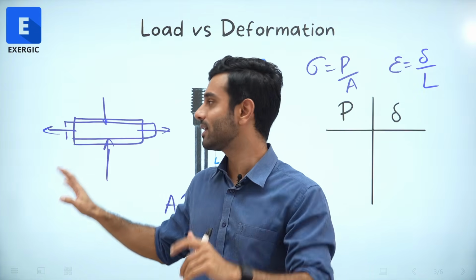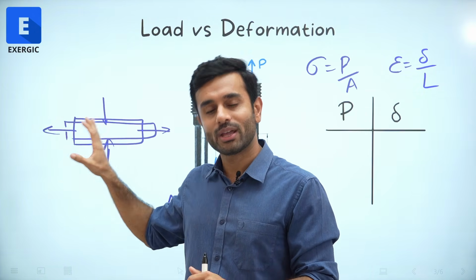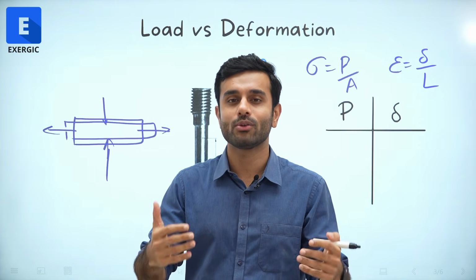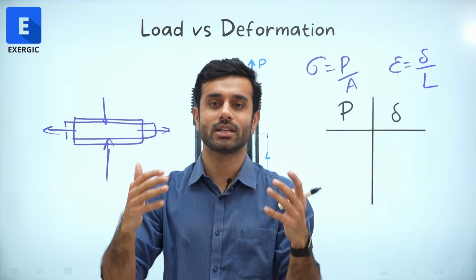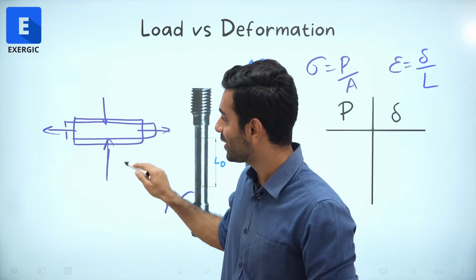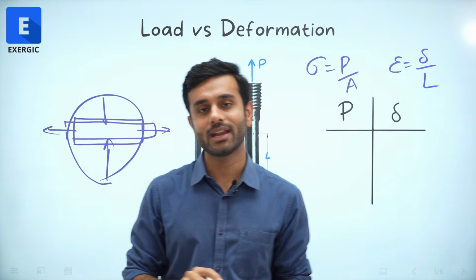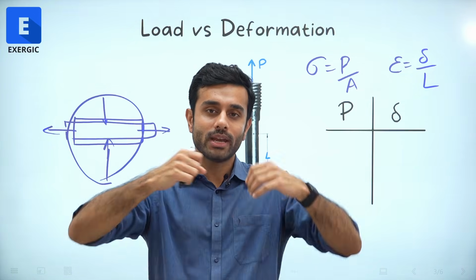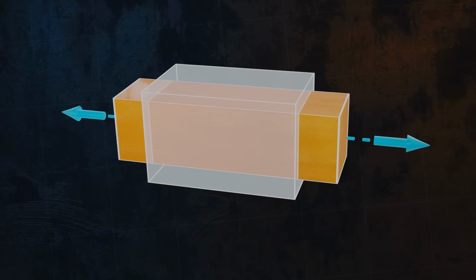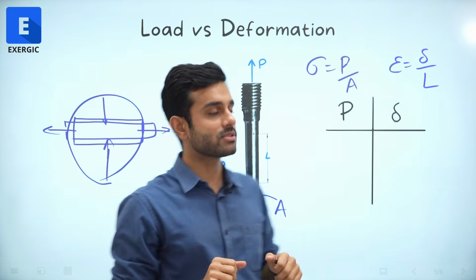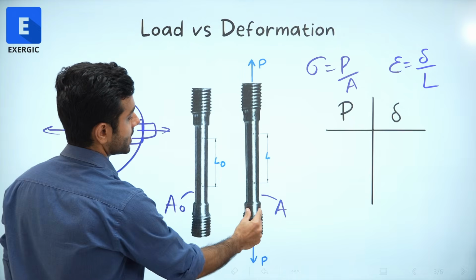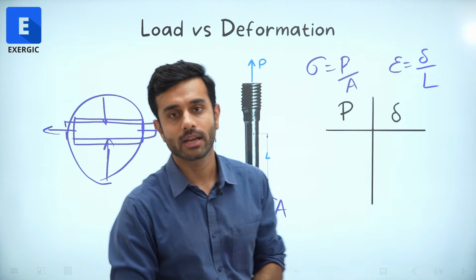We are going to discuss that. There is going to be a separate topic where we are going to relate them mathematically. Right now, I am just trying to link your intuition and feeling with the explanation so that we can proceed. Later on, we are going to come back to this explanation and discuss more about that. So when you elongate along one axis, along length, the perpendicular transverse dimension is going to shrink. The same is happening here. When it is getting elongated, the length is increasing, so the cross sectional area is going to reduce, right?